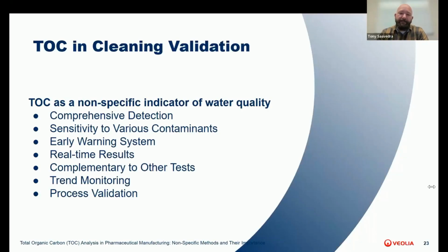Next, its sensitivity to various contaminants. TOC is highly sensitive to many types of organic compounds. It can detect contaminants at very low levels, often in the parts per billion range, making it an ideal tool for monitoring high purity water systems.